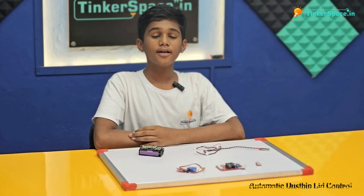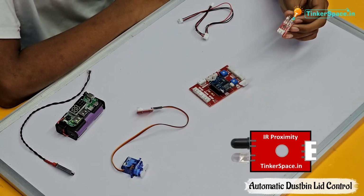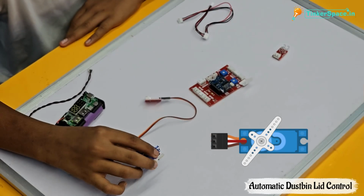Welcome to TinkerSpace. Our project name is Automatic Dustbin Lid. Here we use an IR proximity sensor as input and its function is to detect humans. Here we use a servo motor and its function is to open the lid automatically.